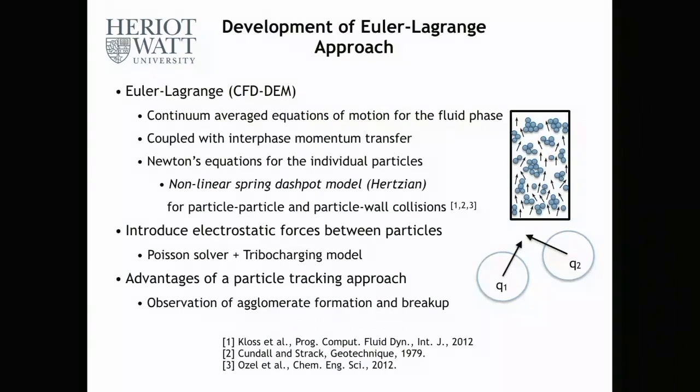So we want to model this flow. What we developed earlier is a Lagrangian approach, namely CFD-DEM. In this approach, we solve local average continuum equations for the fluid phase in an Eulerian field, and we track particles by the Lagrangian approach. In the Lagrangian approach, we solve Newton's equation of motion, and we couple these phases through interface momentum transfer, including pressure gradient and drag force. And we also track the particle collisions.